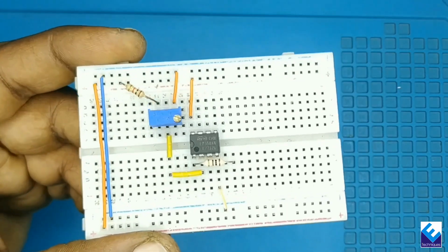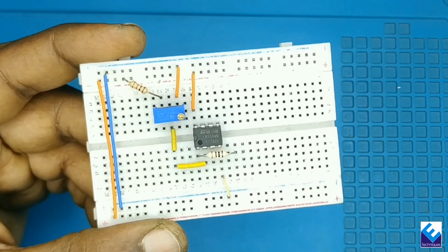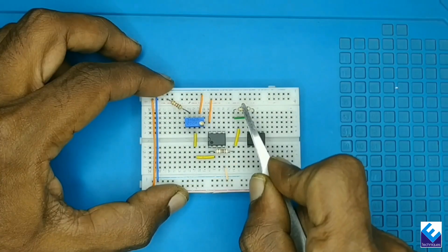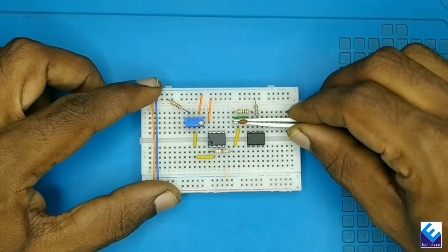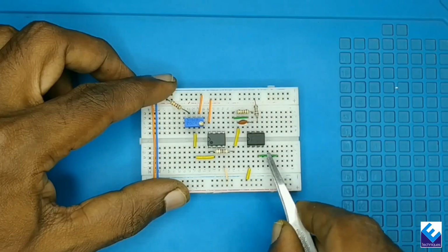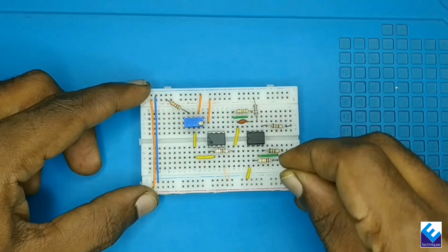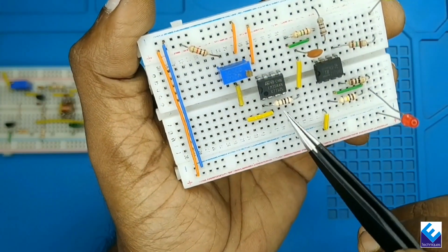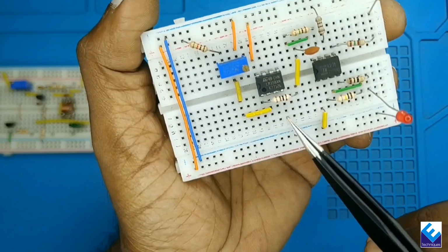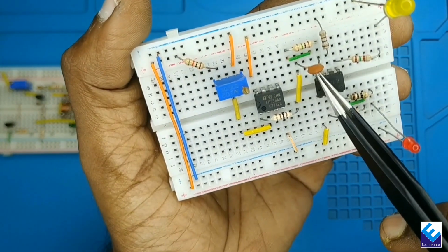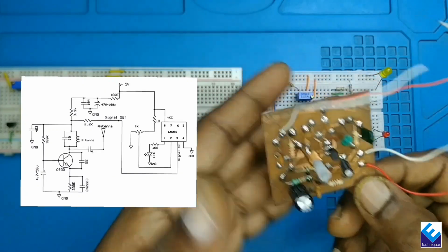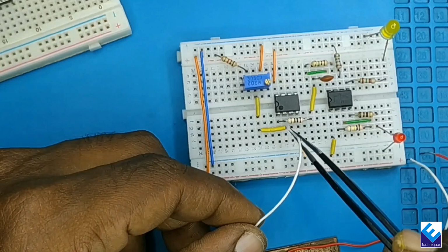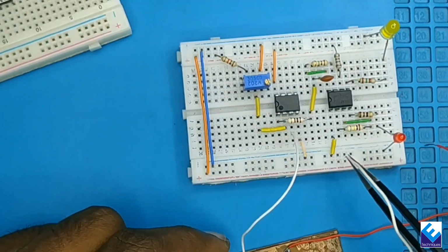Comparator circuit. Making of the comparator circuit was already shown in the previous video. Adding the frequency decoder circuit. The output from the comparator is connected to the input of the frequency decoder through a 100 ohm resistor and the capacitor. RF receiver front-end section, making as explained in the previous video. Connect the front-end section output to the comparator input pin, and connect the positive and negative wires.